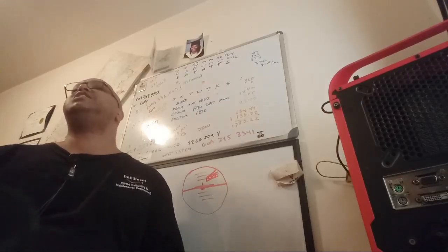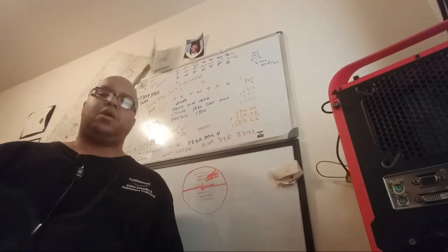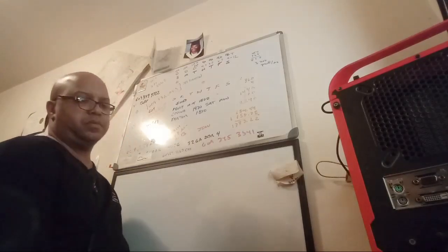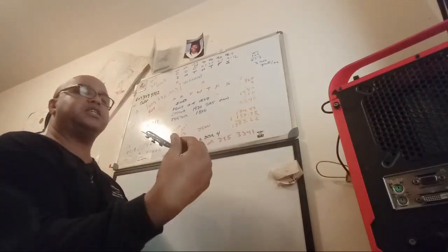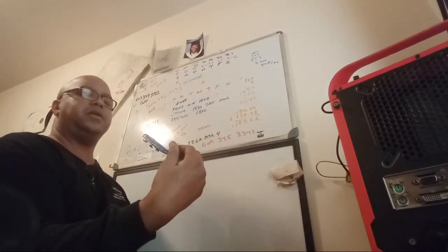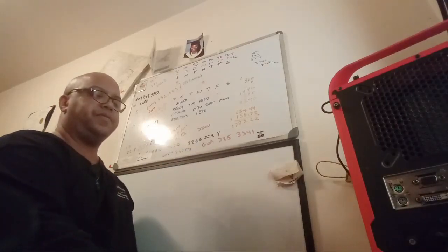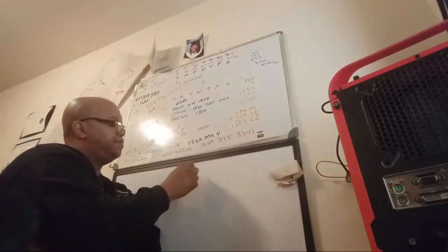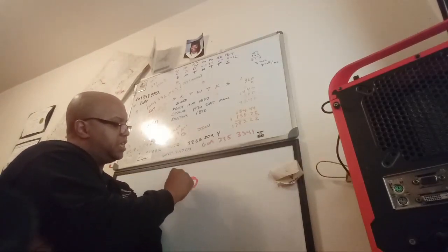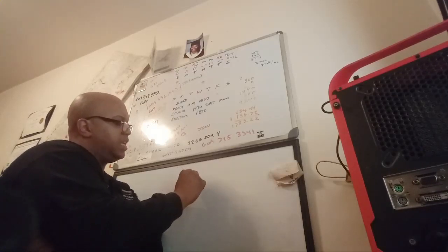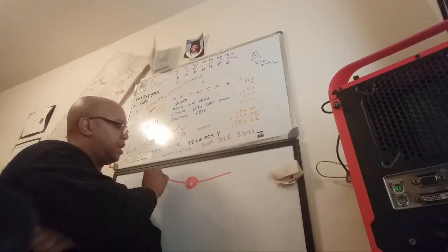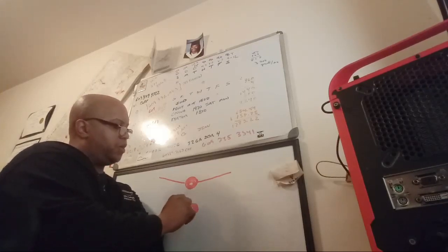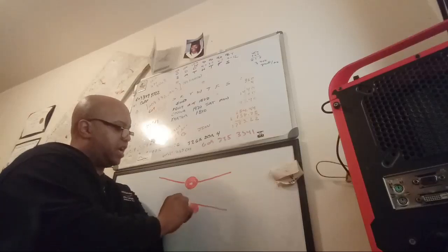Have you ever heard of wing dihedral? In layman's terms, what is wing dihedral? It would be the angle of the wing from its root on the fuselage. Like dihedral wings, instead of going flat out from the fuselage, they go up at an angle. Very good. So here's the fuselage, and this particular aircraft is pointed at us. The wing tips would have a tendency to go upward a little bit, like that, right? That is wing dihedral. What about aircraft like the B-52 or the Harrier? They don't have dihedral, do they?